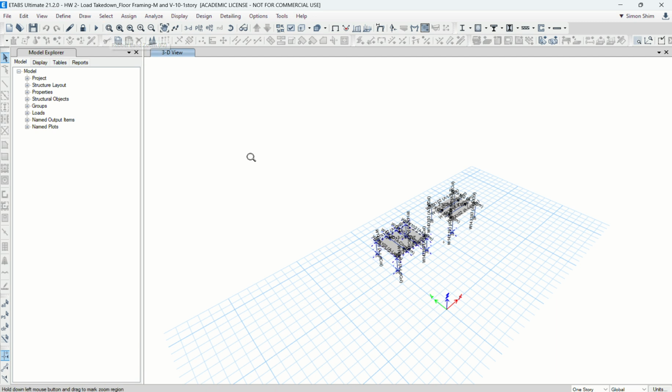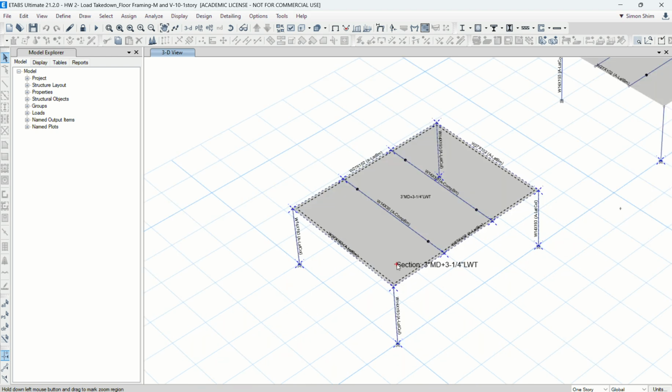So the question is, I will give you just a physical example. This floor framing system is common. We use this analysis everywhere, most likely. But typically, in our buildings, we have a backbone of concrete shear wall, column and beam. All the columns are just straight columns. That means any steel beam and girder is not part of the seismic system. So this is only for the gravity floor framing system. But for this model, I did it intentionally, otherwise it's going to give us instability.